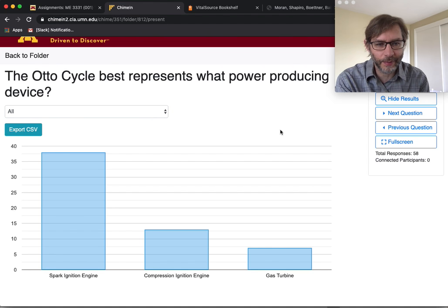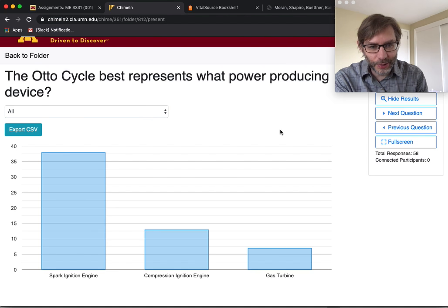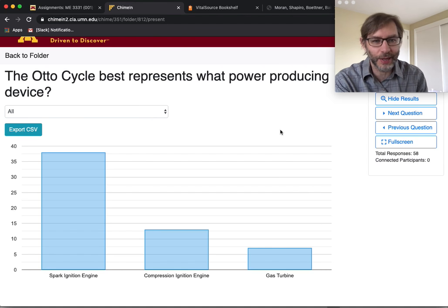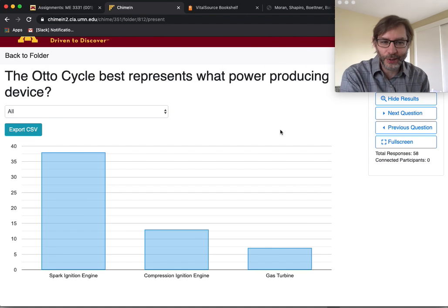One thing I have to point out, since I graded all the exams and problems myself: people are using the ideal gas law to model vapor systems that are in two-phase, like steam. I know the ideal gas law is really easy to use, but it's wrong to use it for a two-phase system. If I say the word steam or water or R22 or ammonia in the problem, do not use the ideal gas law. It just makes me upset, and I just give you a 0. Okay, so that's not cool.